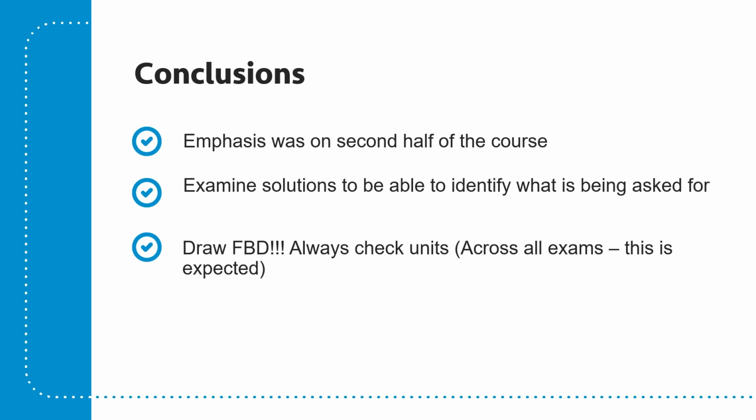One thing I've noticed, because when you correct the exams you see this: draw your free body diagram. It does not save you time. It is not worthwhile writing all of this without drawing the free body diagram. No matter how clever you are, it's always easier to put the axes down, draw the free body diagrams, and always check units. And one thing I'd add on the side of this, always use the right hand rule. No matter what we do to flip things around, always use the right hand rule and then work from there. And once you do that, you're set.